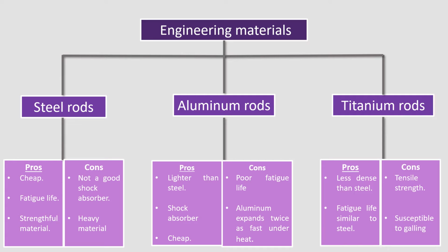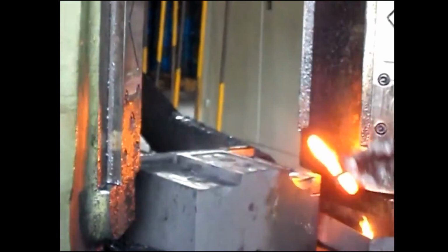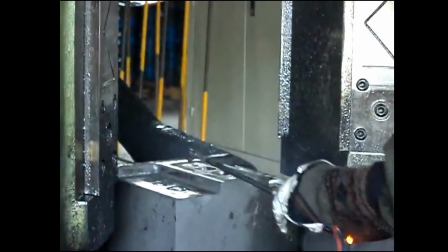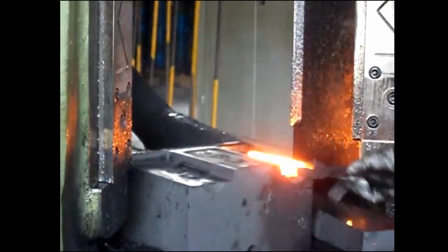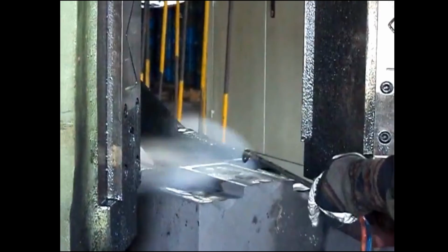Forged rods offer a superior grain structure within the metal, which becomes far more coherent thanks to the large pressures exerted on the rod during the forging process. While aluminum rods follow this process, using casting as their most optimal option. Titanium has been successfully forged by the open die method, using conventional equipment designed for steel, but with lower temperatures and increased pressures. Because of the lower temperature, it becomes necessary to use higher pressures to deform the metal.